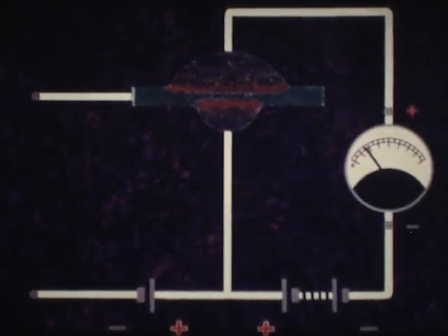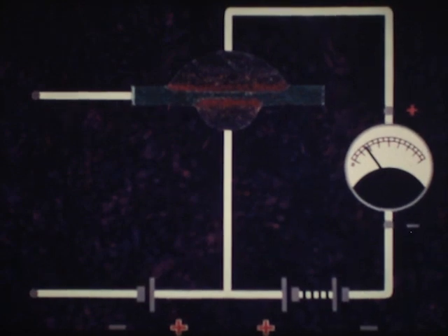By disconnecting the input circuit of this common emitter configuration, a rather large residual current will be seen to flow in the output circuit. This current can be explained by first considering what happens when no external voltage is applied. In this condition, the two barriers are identical in width. However, if the voltage is again applied, the reverse bias of the base collector junction will cause holes to flow into the collector and electrons to flow into the base.